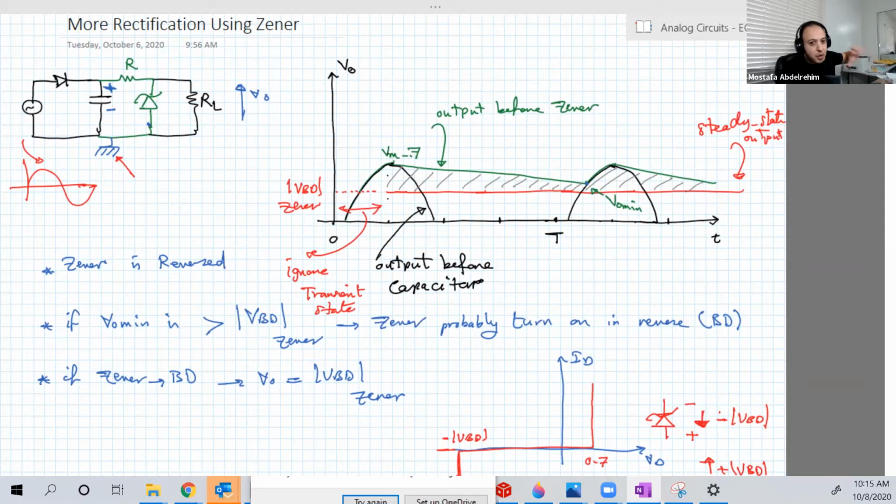If your application is really sensitive to the DC value and really needs the DC value, for example, if the load is a speaker, speakers are usually sensitive to the input signal. So if you want a DC voltage for this speaker, then you should use something like this Zener, and of course you will lose some power. That's not very efficient,